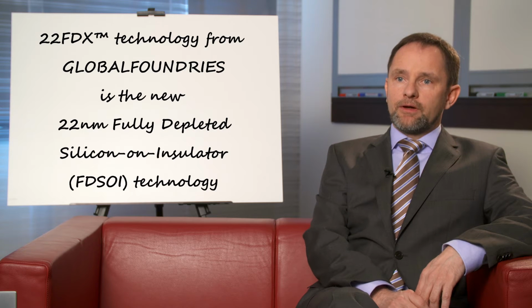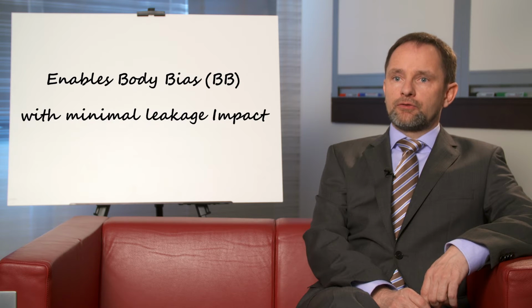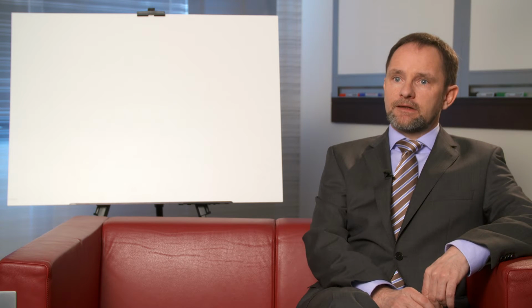I'm a digital design implementation engineer working in the SoC implementation team at GlobalFoundries, and currently our team is working on 22FDX reference flow development. The GlobalFoundries 22FDX technology is a fully depleted silicon on insulator technology using planar transistors, and we are using the body biasing to tune design performance and design power. That's one of the key features of this technology.